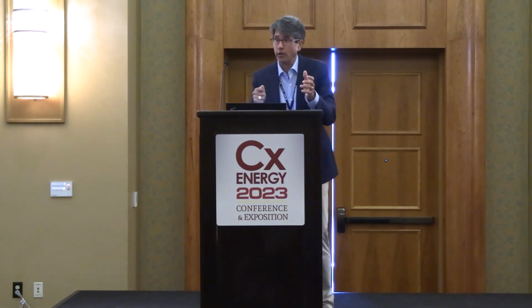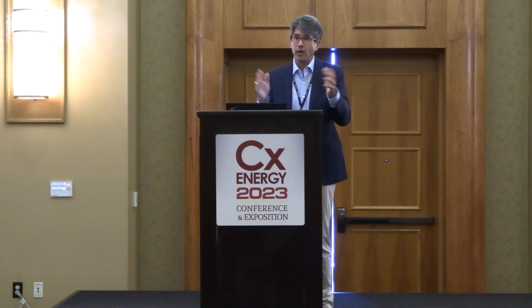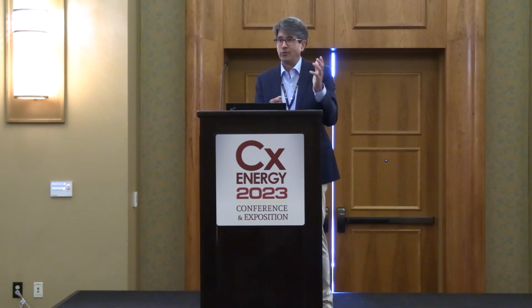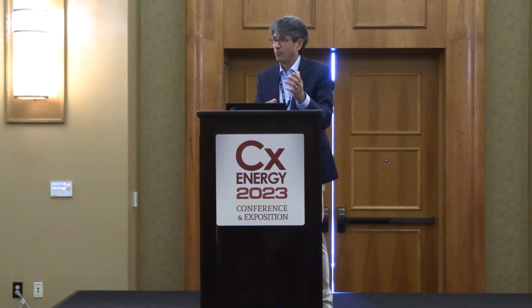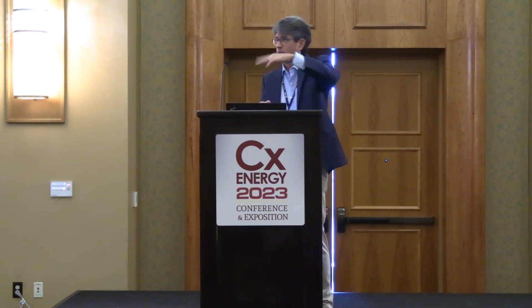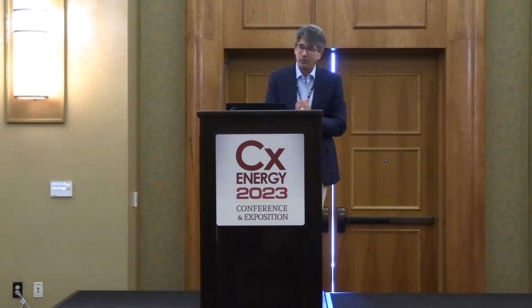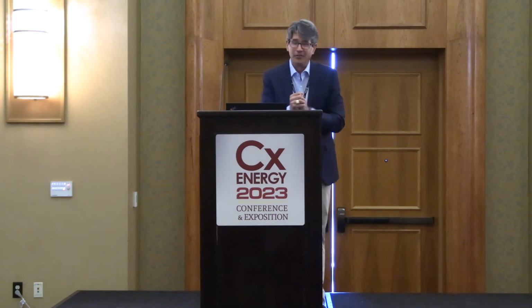You can do what we did, pull control air, and they fell open, right? Great, we're 100% open. Put control air back. We just did the owner a great service on about a 200 VAV job: he now had roughly 100 VAVs that never came back, and he had to replace 100 controllers. We showed him where the failed controllers were, but he wasn't overjoyed at the situation, having to replace them all now. So don't pull the main control air anymore.